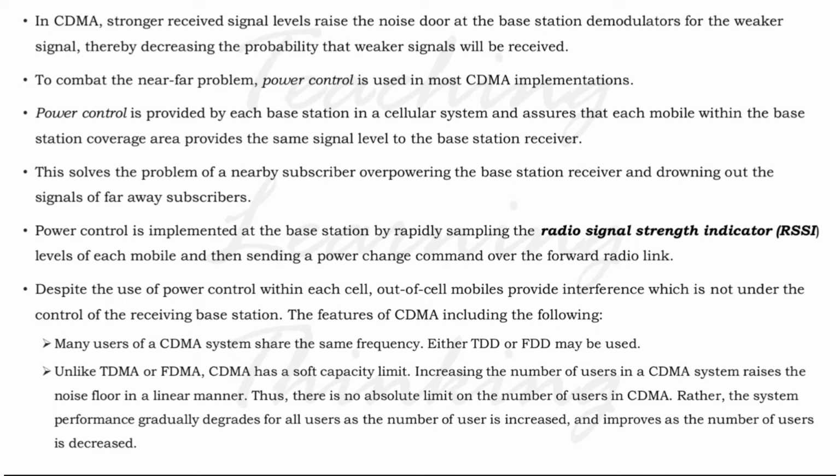either TDD or FDD may be used. And unlike TDMA or FDMA, CDMA has a soft capacity limit. Increasing the number of users in a CDMA system raises the noise floor in a linear manner. Thus, there is no absolute limit on the number of users in CDMA.